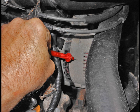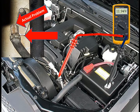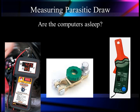Right here, we've got a good ground. Remember, the ground is from the engine ground back to battery negative. We've got 3 millivolts here, practically nothing. And we've got the key on, of course, so we can draw some current flow. Now, in the upper left, this is an actual problem we found. Well, there's the broken harness. This vehicle was in for a flash reprogramming, and it wouldn't flash reprogram. They couldn't figure out why. That's the computer ground.